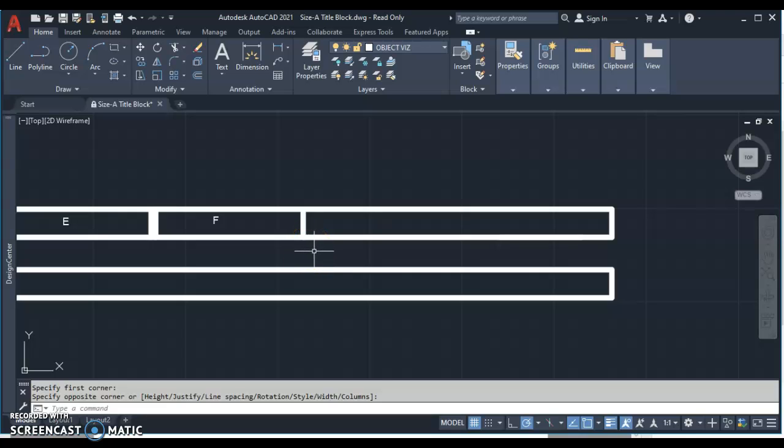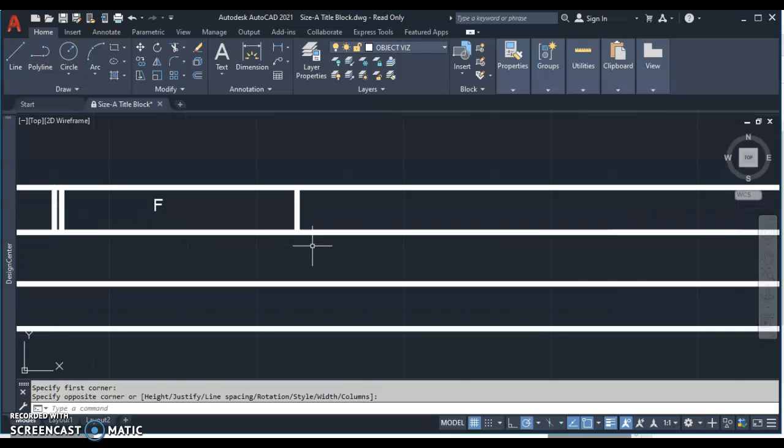Let's consider putting part B. Part B is the rooftop part. It's the longer of the 2 rooftop pieces, and it is 5 inches long. So I'm going to again account for a saw kerf here. So I'll use offset. 0.125 is already in there, so we'll hit enter, and then we'll select the line. We're going to pull it in this direction towards my right, and that creates that offset space or waste space.